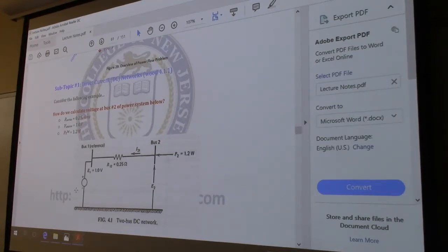So if all the loads in the system, instead of being PQ, we described them as RX, and if we described all the generators instead of PV, we just made them voltage sources, then you could go ahead and apply nodal and mesh analysis to it. But that's not the accurate or the best way of describing the way that the system works, and so we are left with a better description that's going to be harder to solve.